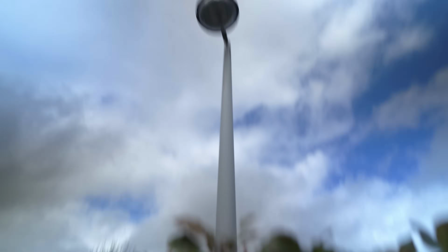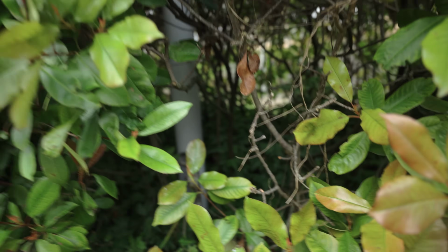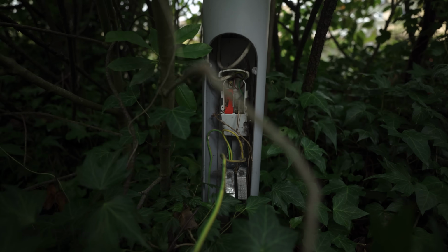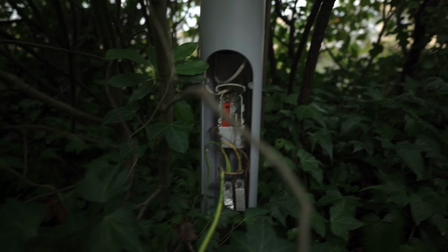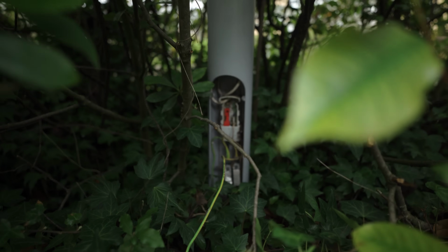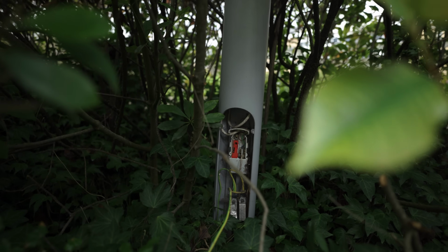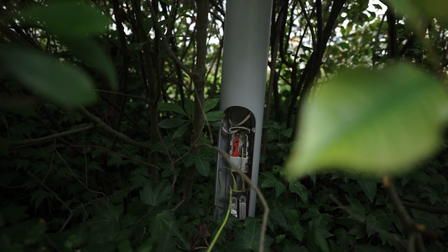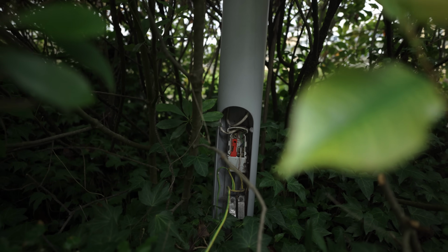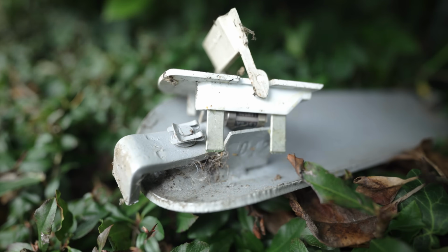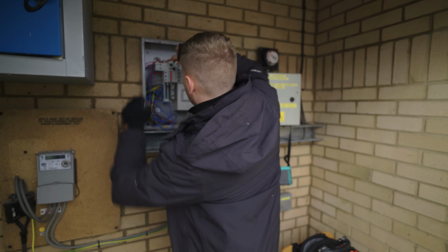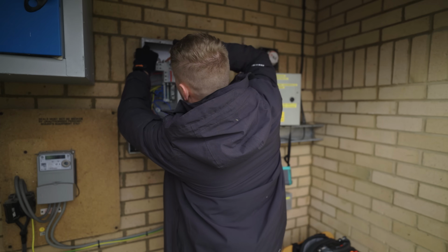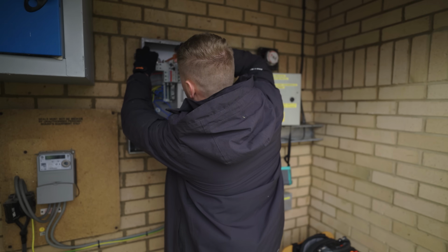So this one's not got its lamp working. That's right, I'm back in the bush. But I mean, it all looks sweet, but either way, I've removed the fuse holder anyway. And now I'll go see if I can get it back in the RCBO and it can hold, because the voltage has got to be coming from the live somewhere, leaking onto the neutral and the earth. So, yeah, maybe it's this one. Let's get this put back into an RCBO.